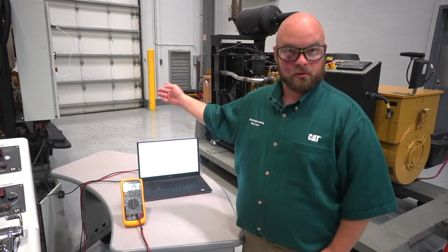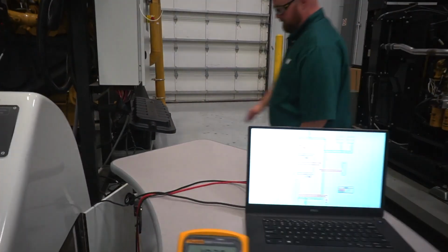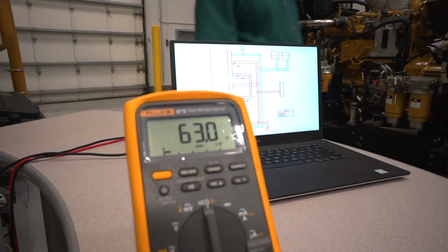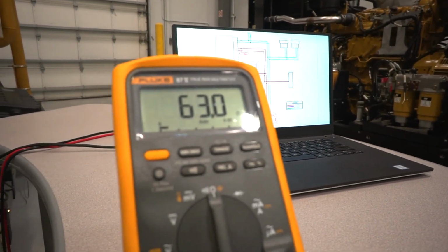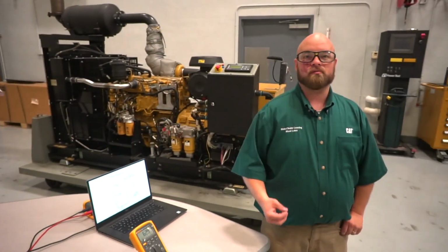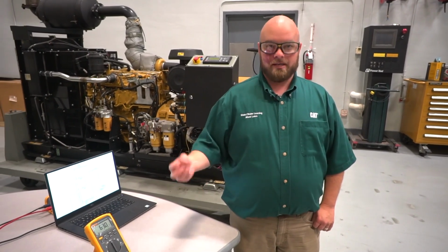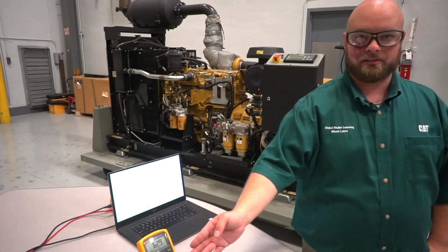So I'm gonna go turn our power off. You watch the meter here. And when we turn the power off, we remove the power from our system, and there we go. There's around our 60 ohms that we would expect to see on a good CAN network if both of our terminating resistors are intact. So by this one little test here, we've checked that yes, our terminating resistors are intact, and our wiring, at least to the service tool connector here at this point, is also intact.